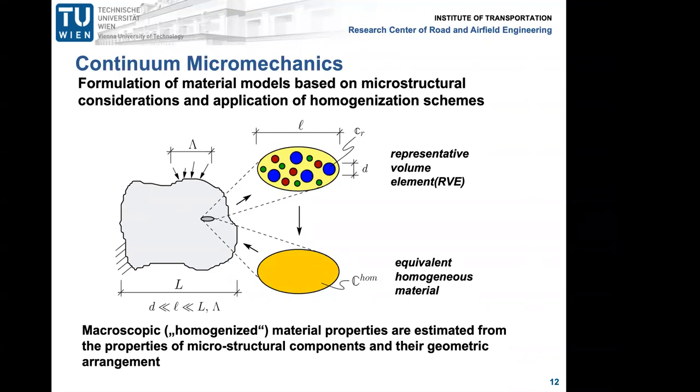And to determine the homogenized mechanical behavior of the overall material, the correlation between the homogeneous deformations acting on the boundary of the RVE and the resulting averaged stresses is estimated by using the elastic or also the viscoelastic behavior of the material phases of the RVE, as well as the volume fractions of the different inclusions, and also the characteristic shapes and the interaction.